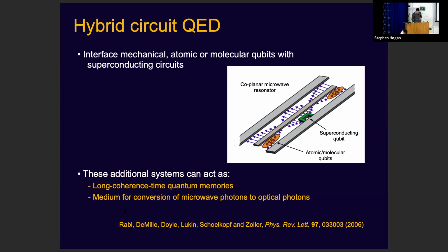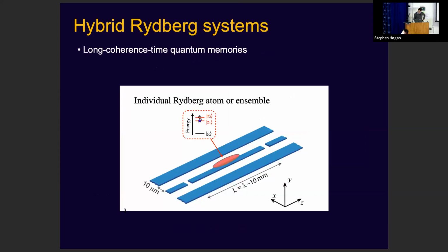So then from a Rydberg perspective, I'll show you our resonator is a little bit differently designed, but this here is a resonator. So the center conductor is split at this place here and at this place here. So these are capacitive joins and they act as mirrors of the resonator. For the microwaves, this is like a mirror, and this is the other mirror at the other end of the cavity. And the idea here is that we would have a cloud of Rydberg atoms or a single Rydberg atom above the resonator. And if you wanted to implement this maybe as a quantum memory, you could think about using the transition between two Rydberg states at the microwave frequency that's resonant with the resonator frequency. And that would be the qubit transition in this memory.